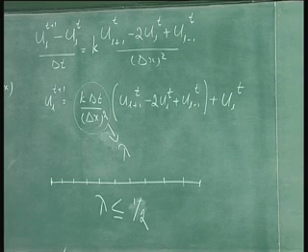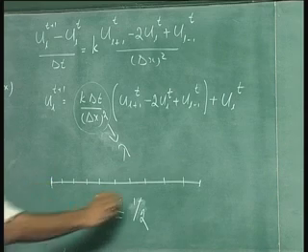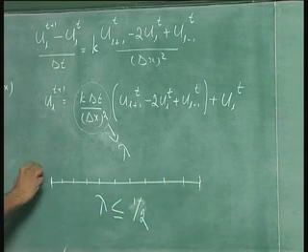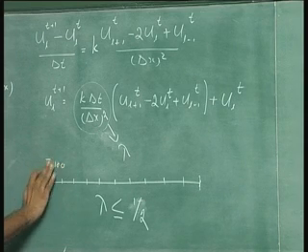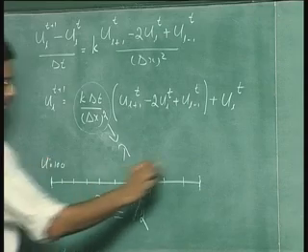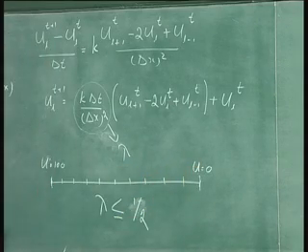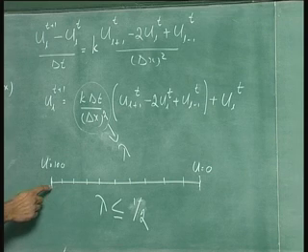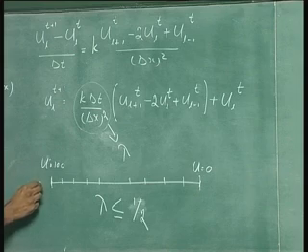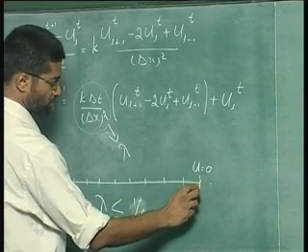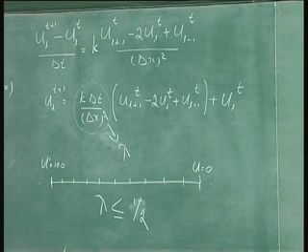So we have to use some boundary conditions. The boundary condition could be that at the two endpoints the temperature is specified. So we could say u is 100 here and u is 0 here. Or we could use the derivatives at the two boundaries. If we fix the derivatives at the two boundaries and get the temperature corresponding to two fictitious points on that side, so that the derivative can be fixed, then we would have to solve for all the points including the boundary points.